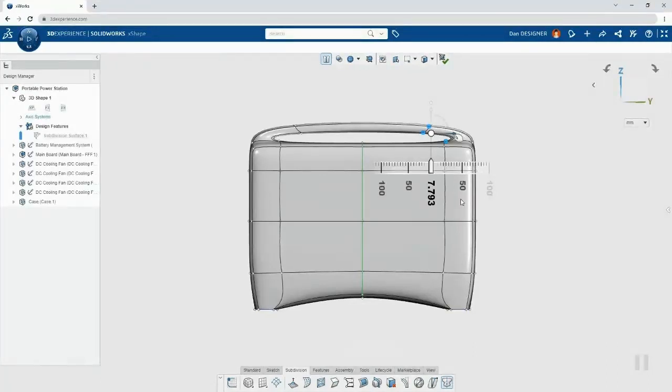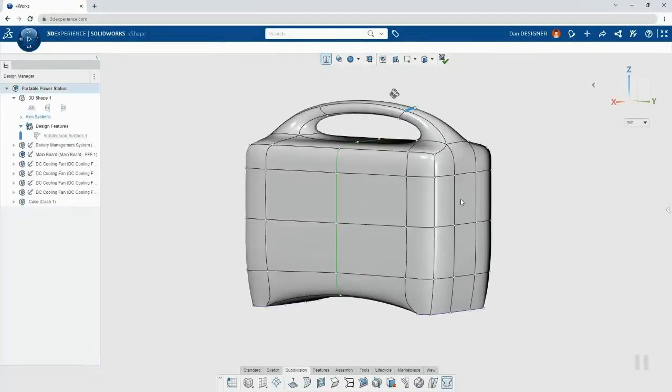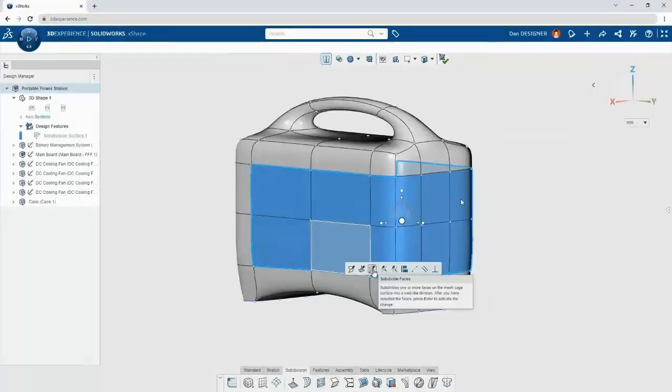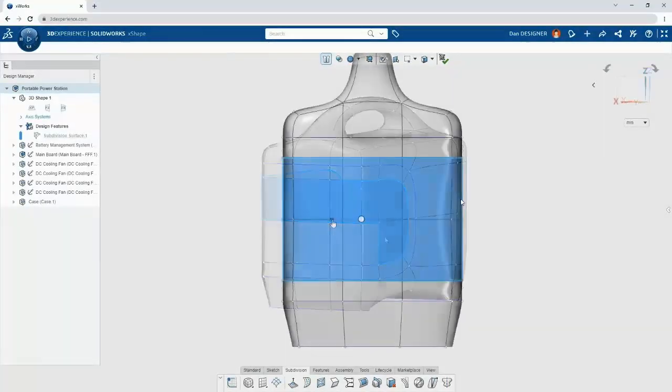Now, that geometry may not be perfect. We may have to go in there and rotate it. So again, those control points are not just for XYZ movements, but they're also for rotations. In this case, by taking those 2 pieces of clay I hooked on each end, I can connect them very easily. And this is where the control point power comes into play. Watch how we can adjust the thickness, location, and geometry of that handle just by connecting 2 things.